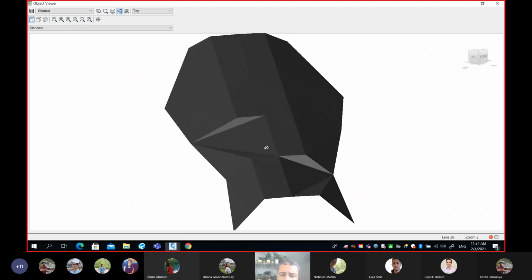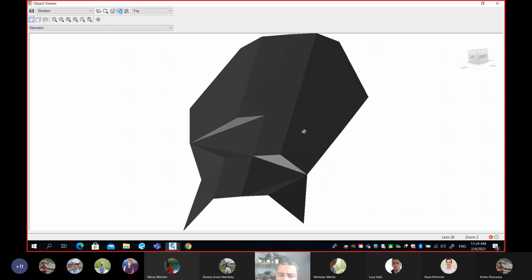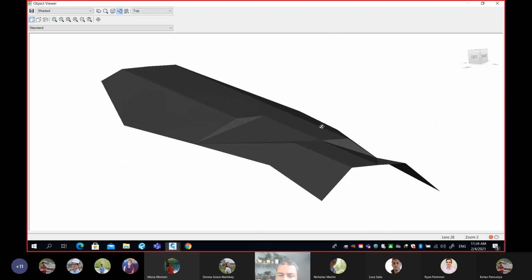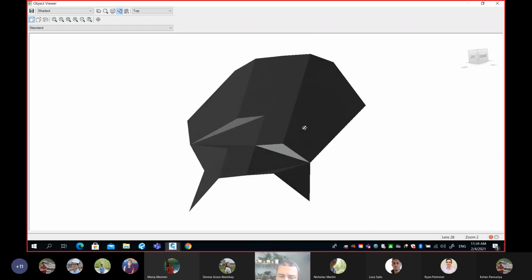Look at this. There are some triangles. They went from the center line straight to the end of the side slope: one point here, another point here, and those points are the center line. And then the third node is at the end of the side slope. Shouldn't happen. Now, why am I doing this? To show you the importance of break lines. If you have a problem, or you cannot see the problem, let me know now, because the next discussion is we're going to work on our project or our surface and fix it.